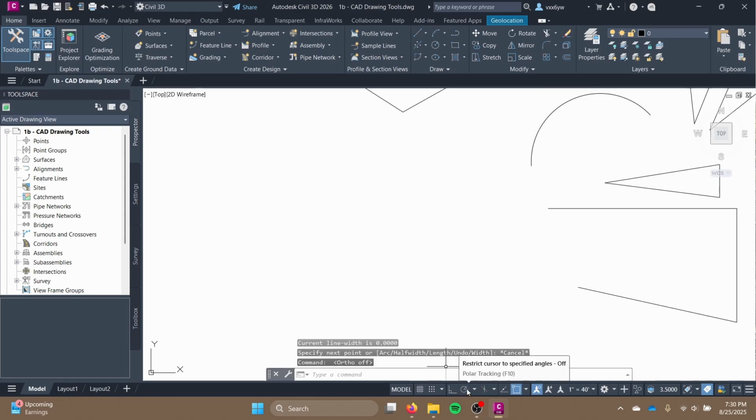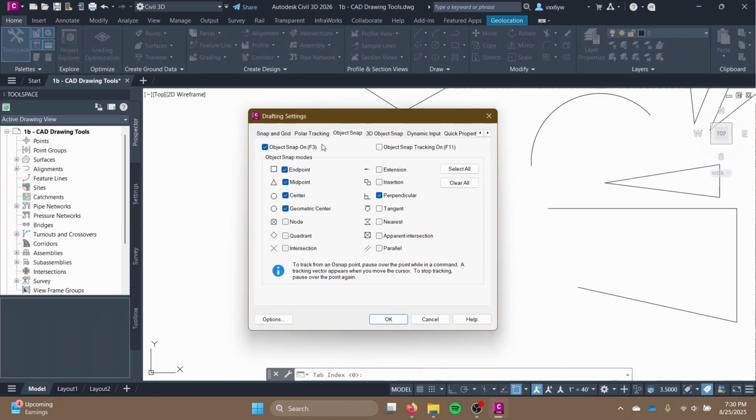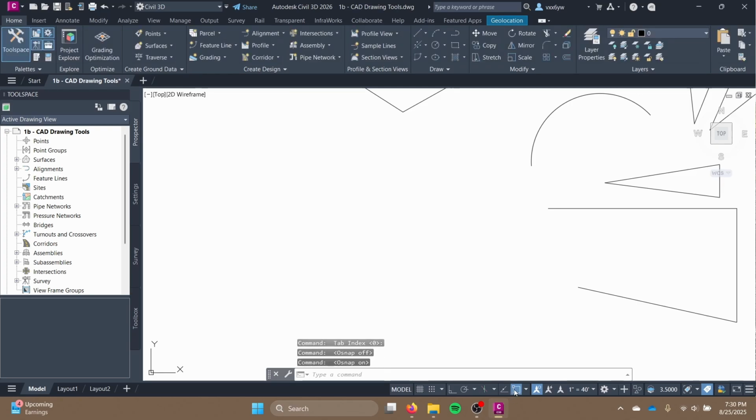There's a similar one for any kind of angle. The most important control down here is this one, though, called snap cursor to reference points. If you open this and open the snap settings, you can see all of these different settings to snap on. Endpoints, midpoint, centers. If you are ever trying to get a line or an object to be in not a quote-unquote easy spot, then I would check here first, and I would turn that off by either pressing the button or pressing F3. That does it as well.